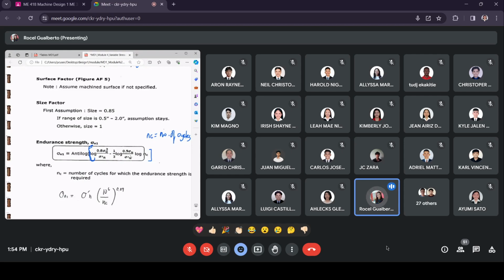And then, here, you have their sigma prime n. Okay? Again, this is your endurance limit. Yung diniscuss natin kanina on the indefinite life. The same lang po ito. So, even though it's a definite life, you still need to determine sigma prime n. So, hindi po tayo doon nakaligtas. May sigma prime n pa rin pong involved po dito sa definite life. And then sigma u, of course, would be our ultimate strength.